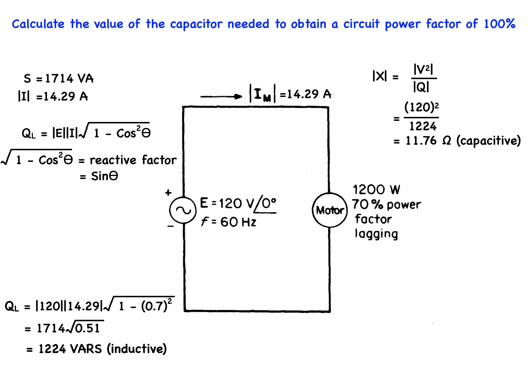Remembering that the magnitude of the capacitive reactance is given by the formula XC is equal to 1 over 2 pi FC. Remember that we are trying to find the magnitude of the capacitor. Therefore, we bring our unknown capacitance to the left of the equation and all of the other known quantities to the right-hand side of the equation. And we get C is equal to 1 over 2 pi F times XC.